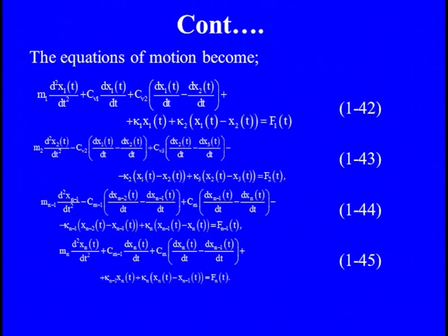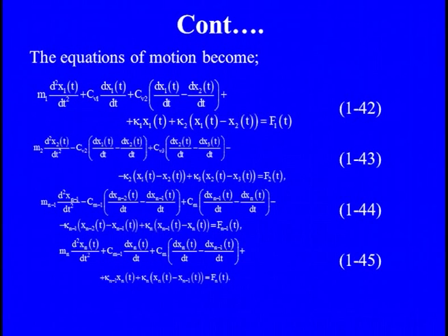So the force vector on the right hand side of equation 1.36 is made equal to 0, and then in order to calculate the undamped natural frequency, we need to keep the damping factor 0. So in general terms, our equation 1.36 will be equal to minus omega square M xp plus K into xp equals 0, and this equation will give you the undamped natural frequency, the characteristic roots, which simply reflect the spring and mass system.